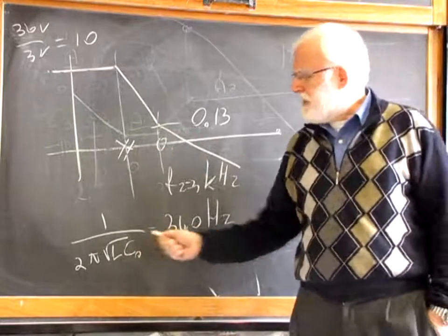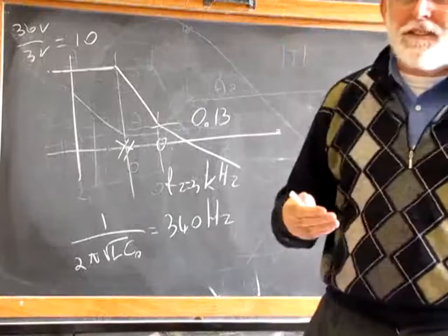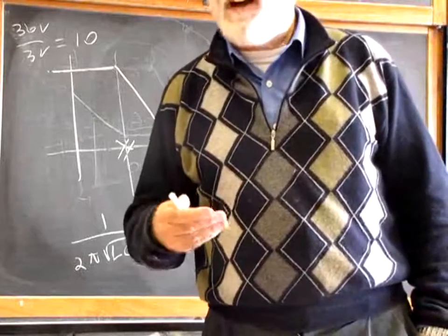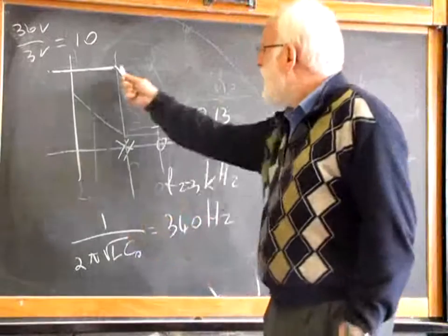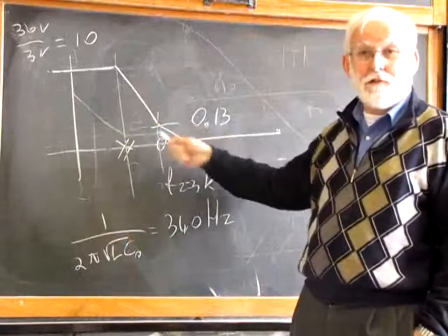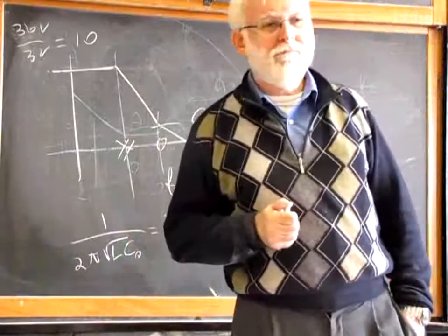Well, it's not 300, it's 340, so we have to remove a little bit, more than 10%. Let's say 10%, that is 9 times. 9 squared, because this is a double pole, so we need to square the frequency ratio. 9 squared is 81.